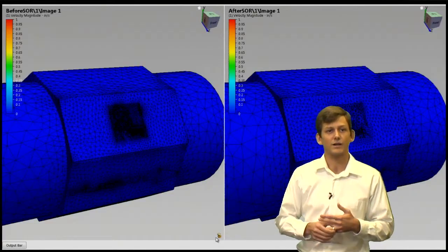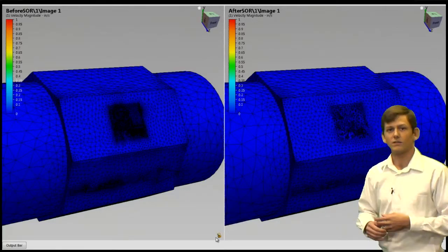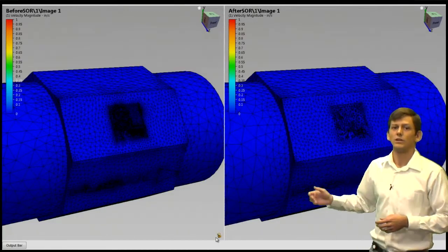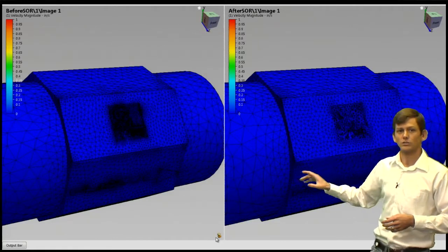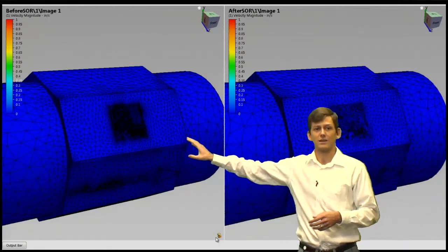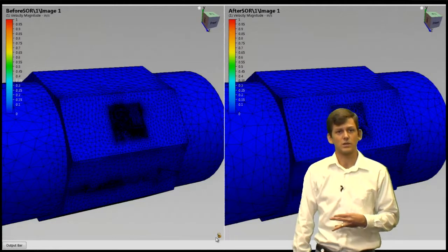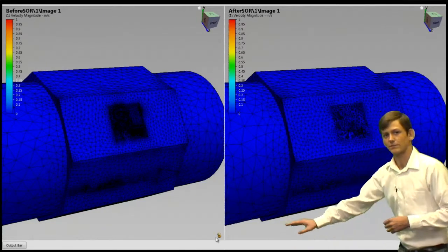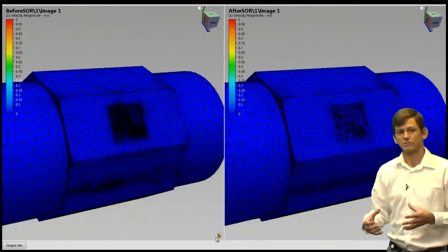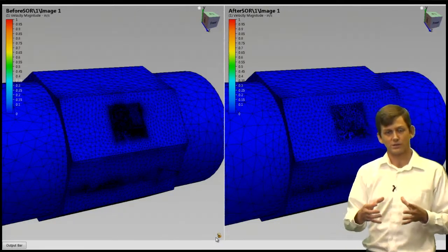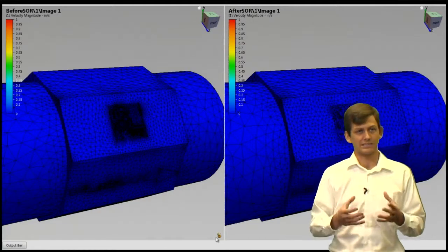as we saw in the little preview of the PowerPoint, some of the effects of this. So looking at that logo, here you can see that the mesh surrounding the logo is notably coarser than the mesh surrounding where the actual logo was previously. If you see it as well at the bottom, here's one that was untouched with a small object removal. So this is just some features that are concentrating elements that we may not actually need in our analysis.